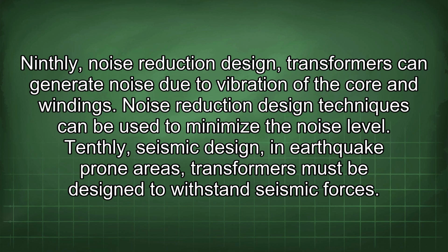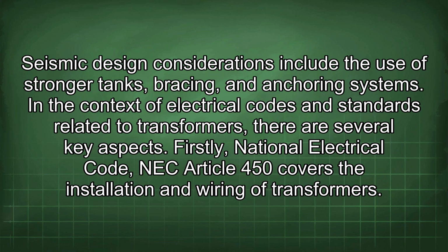Transformers can generate noise due to vibration of the core and windings. Noise reduction design techniques can be used to minimize the noise level. Tenthly, seismic design. In earthquake-prone areas, transformers must be designed to withstand seismic forces. Seismic design considerations include the use of stronger tanks, bracing, and anchoring systems.